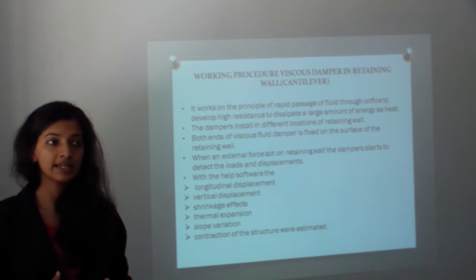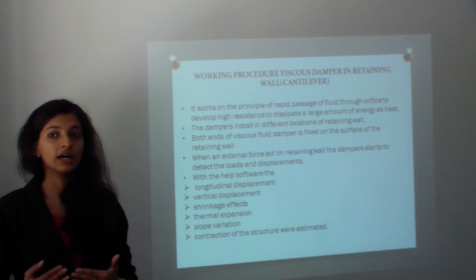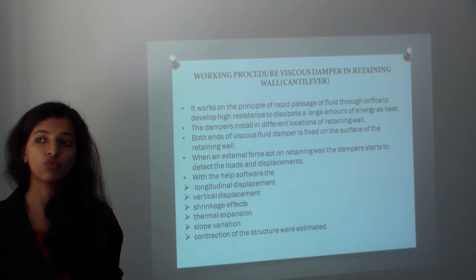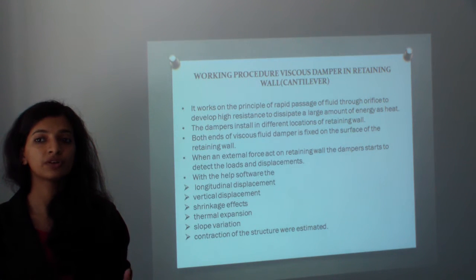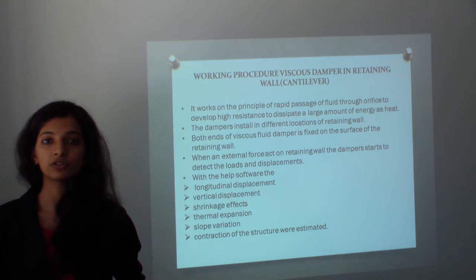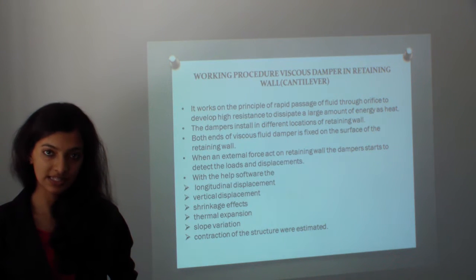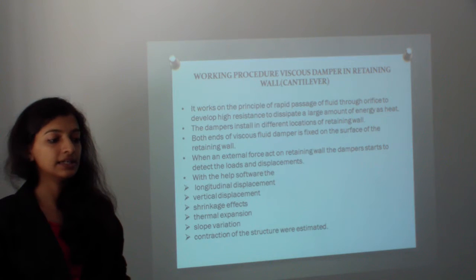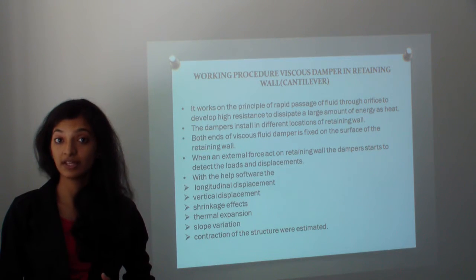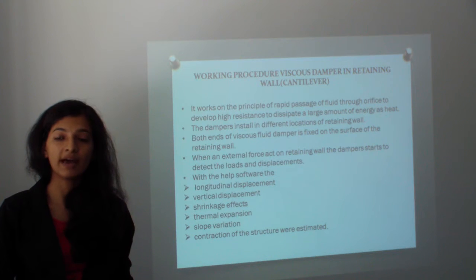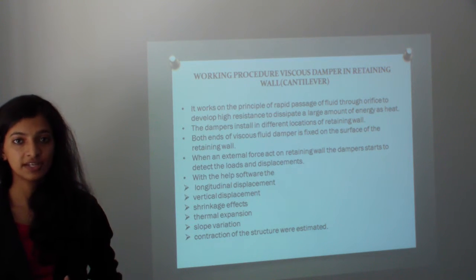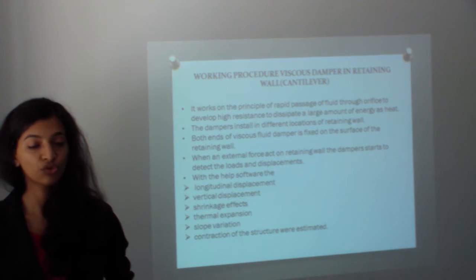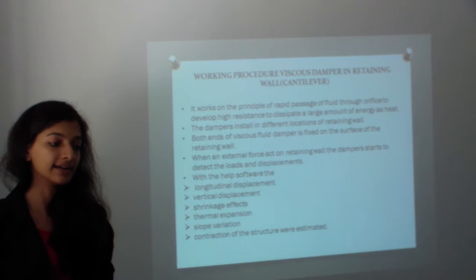I think, in my opinion, my research, the dampers used in the wall can also be preferred for the retaining wall. It also may be effective to avoid the seismic effect on the retaining wall. Actually, viscous dampers are mainly used in ordinary wall. The same dampers can be applied in the retaining wall, and it works on the principle of rapid passage of fluid through the orifice, as we said earlier.